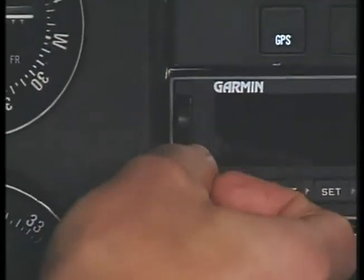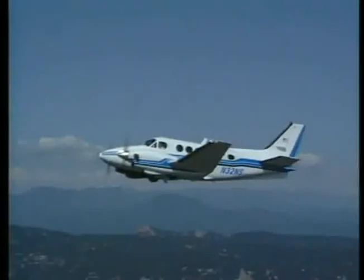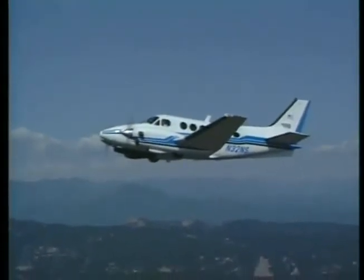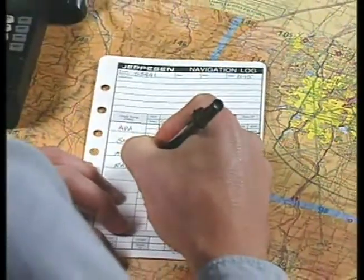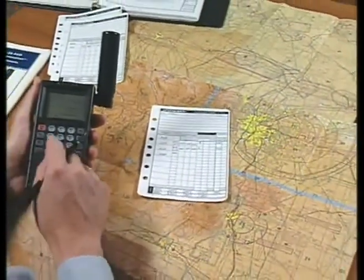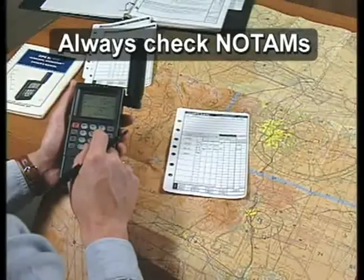Flying with an outdated database is like using an expired sectional chart. In fact, to fly IFR by GPS, you must have a current, updatable database. Since both airspace and navigation data are constantly changing, you should apply this requirement to VFR GPS use as well. GPS is rapidly becoming the standard means of navigation. Take the time to become familiar with the unit you will use, planning your flights carefully prior to departure, and when possible, programming your GPS on the ground. In addition, always check NOTAMs for any outages in the GPS system that would affect GPS navigation.